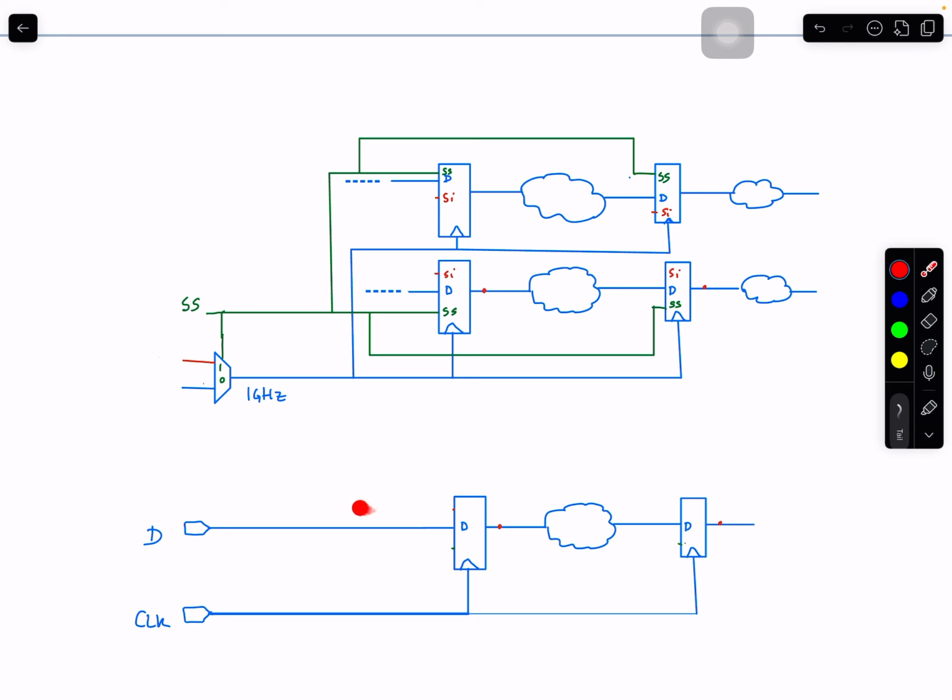Now, if there is any kind of interface happening, because maybe this clock is generating some enable signal or maybe there is some sort of data transfer with some synchronizer and all that, then you will know if those come in your timing violation or not. If they come in timing violation, and you think those are not valid, you add some more MCPs on the setup and hold. If not, you don't worry about it. You can create false paths. So, if there is minimal interaction between these two modes, I would rather, instead of creating another completely separate mode, create just one functional mode with both JTAG and functional inside, which is what we did.